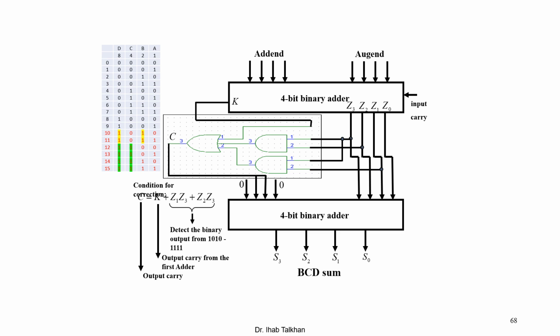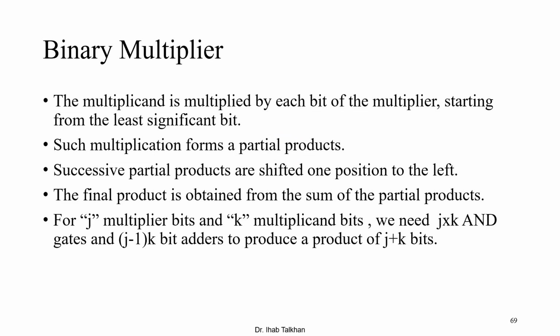This is how we built the BCD addition, and as you can see, it came from your knowledge. You don't have to do any type of K-maps or equations or truth tables. It actually came from your knowledge about how to add BCD numbers, what the structure of the BCD coding system is, and the properties of the AND gate and the OR gate.